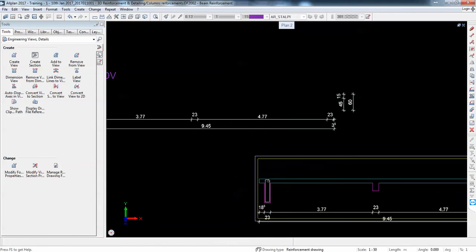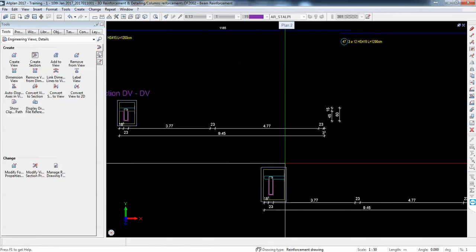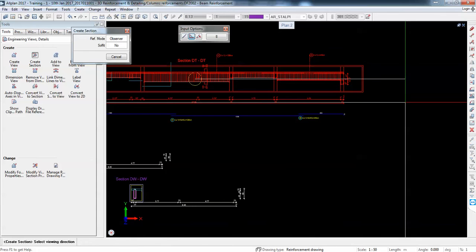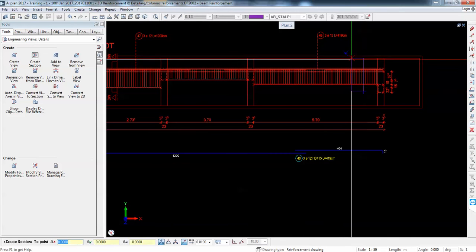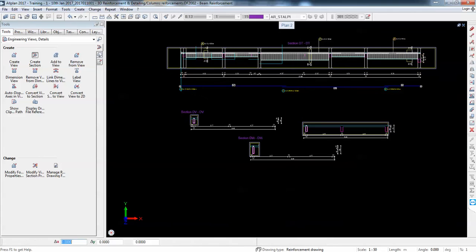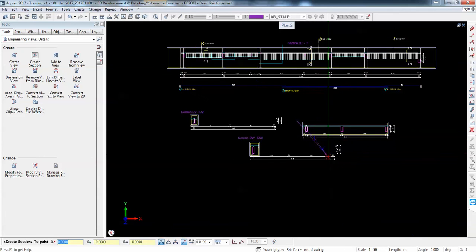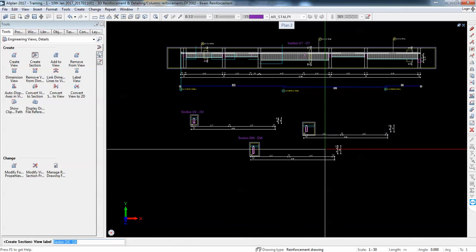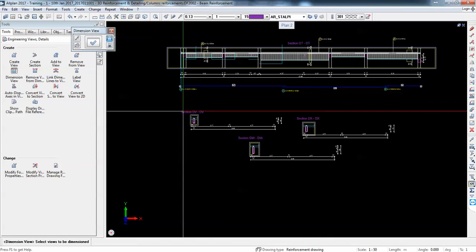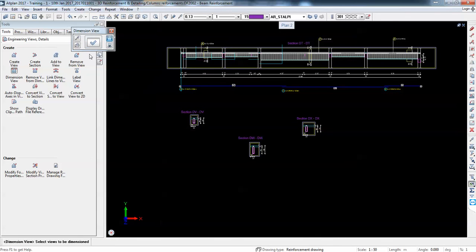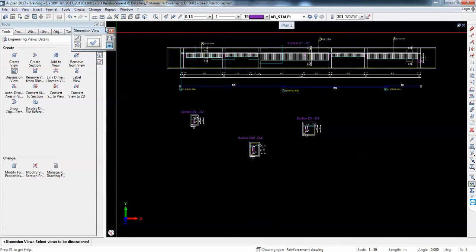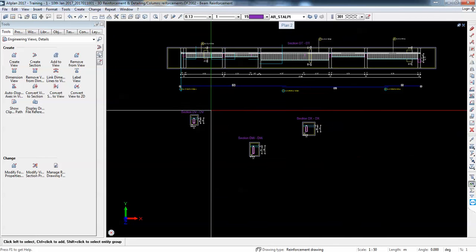But you'll see it's no problem when it comes to detailing or adapting to have better representation. But the first stage is to obtain the first full cage for one beam, and then we will adapt for all the others. To fix them, we'll just go like this. I say dimension view, and it will place the dimension views. I don't want those yet.